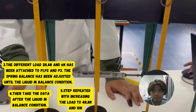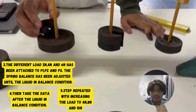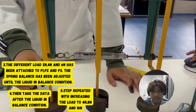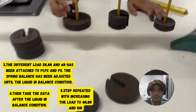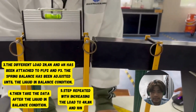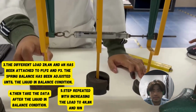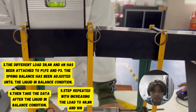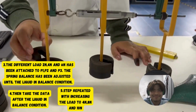Third, the different loads 2 Newton, 4 Newton and 6 Newton have been attached to P1, P2 and P3. The spring balance has been adjusted until the liquid is in balance condition. Fourth, then take the data after the liquid is in the balance condition. Fifth, the step is repeated with increasing the load to 4 Newton, 8 Newton and 10 Newton.